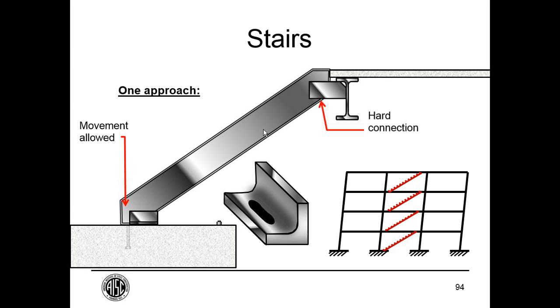The detailing of typical stairs, I think, at least in California, has allowed for this sort of relative movement for pretty much my whole career. Now, if you have a building that was designed in 1950 in St. Louis, people weren't thinking too much about large seismic motions, and nowadays, if you're designing in St. Louis, you are. That may be problematic. It may not be the most problematic thing about that structure, but it may be. And the remedy, I don't think there's a standard remedy for that at all.